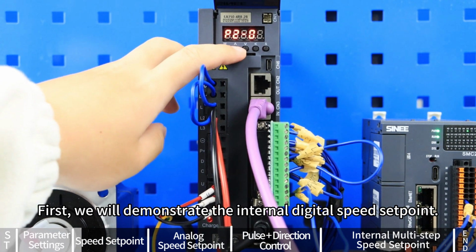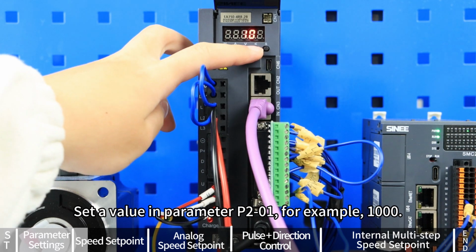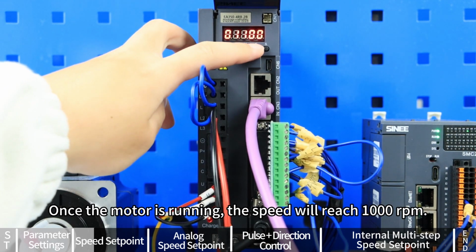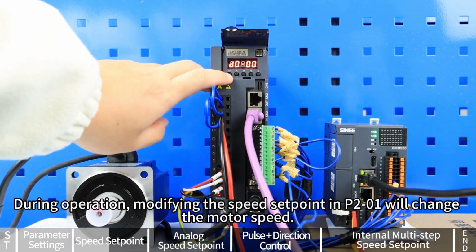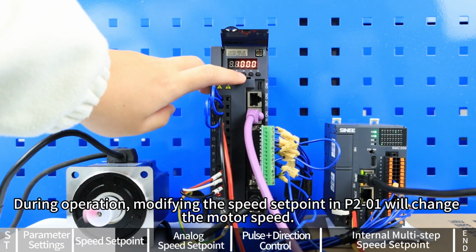First, we will demonstrate the internal digital speed set point. Set a value in parameter P201, for example, 1000. Once the motor is running, the speed will reach 1000 revolutions per minute. Send an enable signal to the drive from the host controller, and the motor will run at 1000 revolutions per minute. During operation, modifying the speed set point in P201 will change the motor speed.